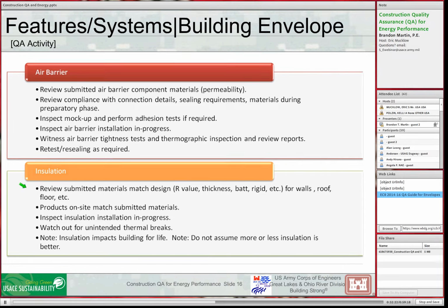Insulation, we need to make sure that the materials match the design. The products that come on site match what was submitted. We need to make sure we watch out for unintended thermal breaks. Is there insulation that is being broken by structural members that was not intended?